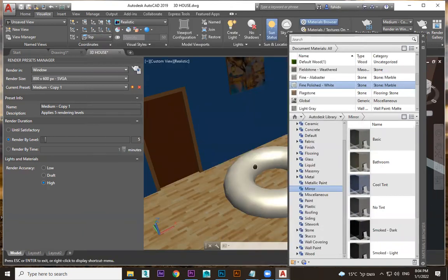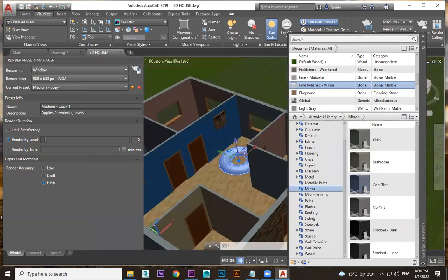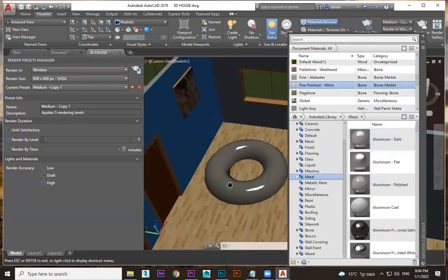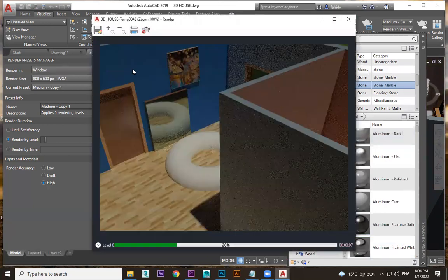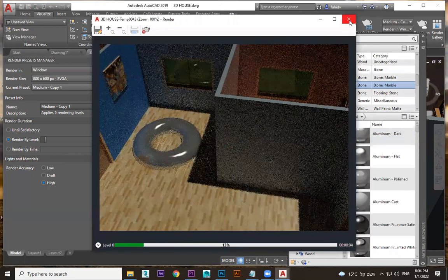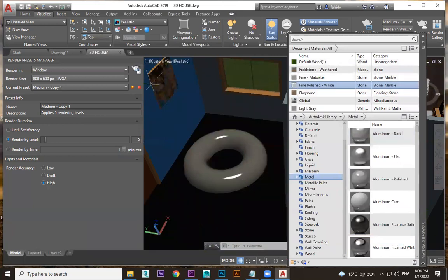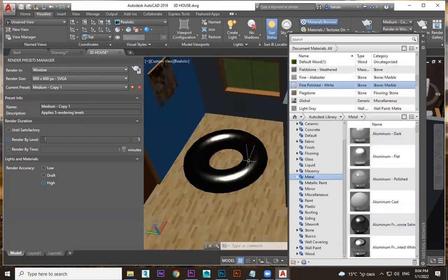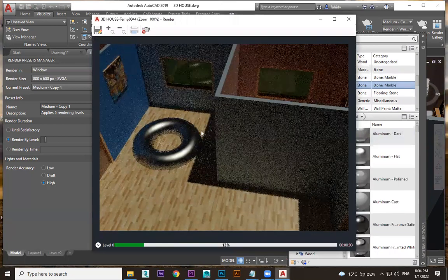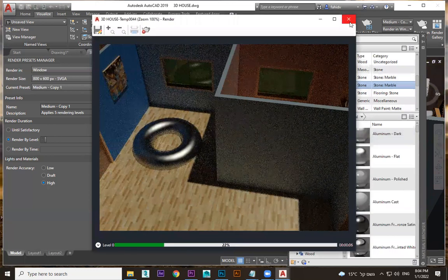You can check that. And something more, you have a chrome material, like you have a handle and all. Metal material, steel, chrome kind of material. It is nice, aluminum material. All this you need to render one by one with very good lighting. Then you can see the difference in it. This is one. The reflections are very important. Let me try this. Because the reflections are important, if there are no reflections near it, you may not get a proper result.